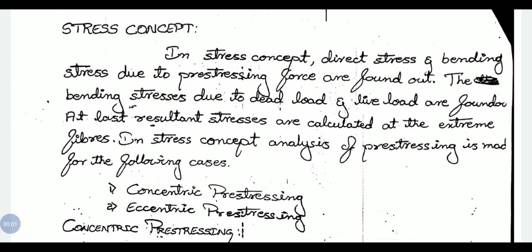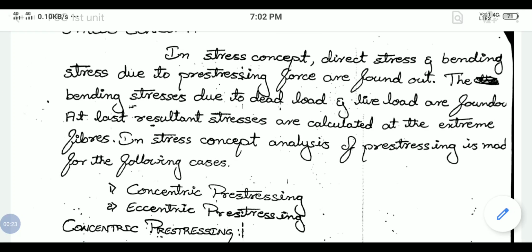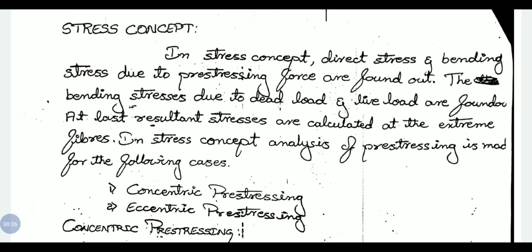Good evening, everyone. Today we are discussing the different methods of analysis of pre-stressing force. In that first one, we are discussing the stress concept. In stress concept, the main thing we are concentrating on is the calculation of stresses developing due to pre-stressing force and stresses developing due to dead load and live load. In this concept, we are considering all the effects of pre-stressing force as well as dead load and live load.